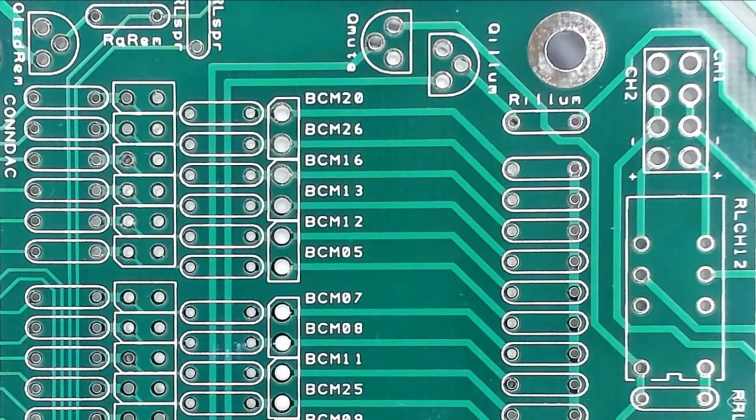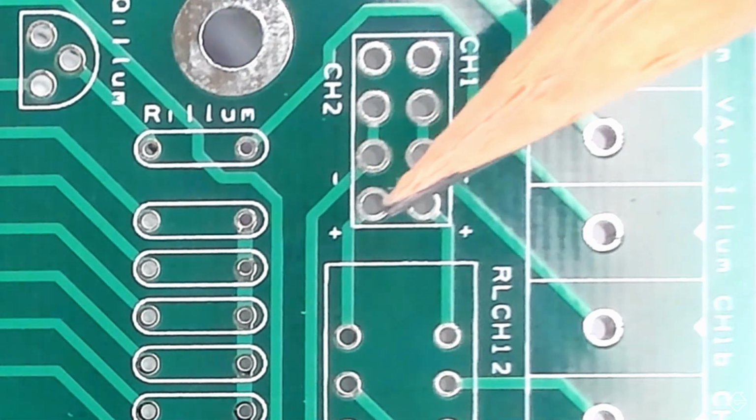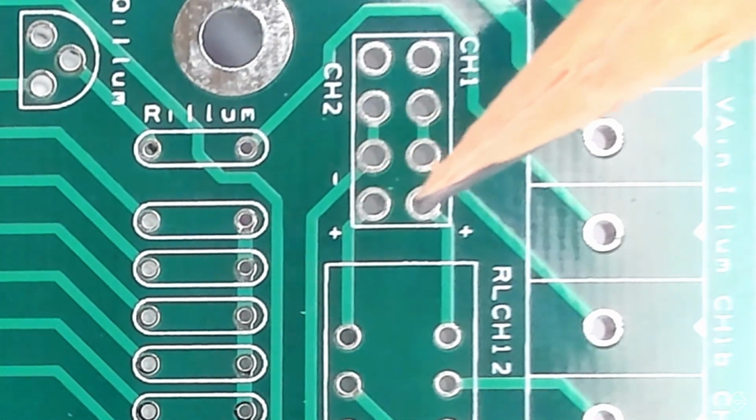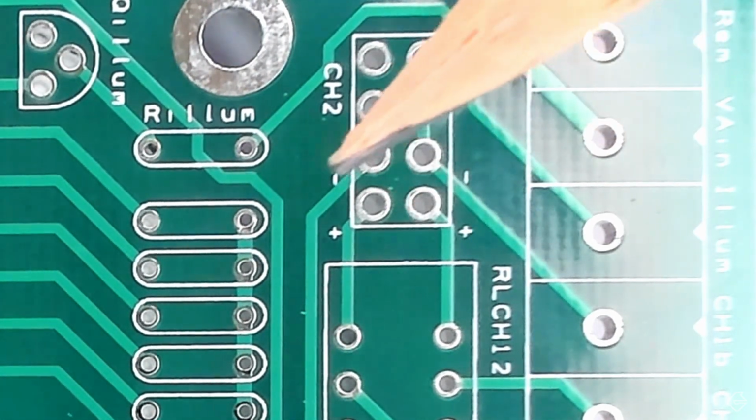But that's not all. Take a close look at this PCB and take a close look at some of these holes. Let's choose this one over here where my pencil is. See how there's a hole in there and you can kind of see through it, but look immediately outside that hole. There's a little ring of metal. And that ring of metal is very important because that ring, first of all, gives us electrical connectivity to the device, but it also allows us to anchor the device.